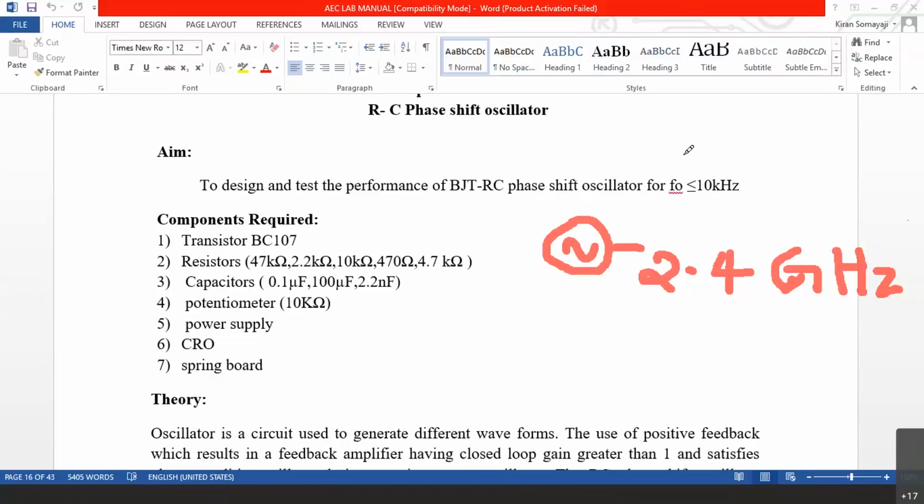But it is going to introduce a 180-degree phase shift, and then it is going to take a small portion of the output back to input. At the same time, it is going to be a frequency selective network. Now, when it is frequency selective, even though the device contains all types of noises from 0 till infinity, all types of noises, because noises do not have any particular frequency.